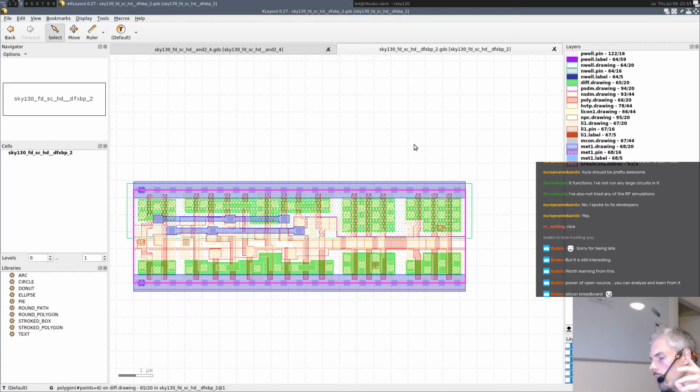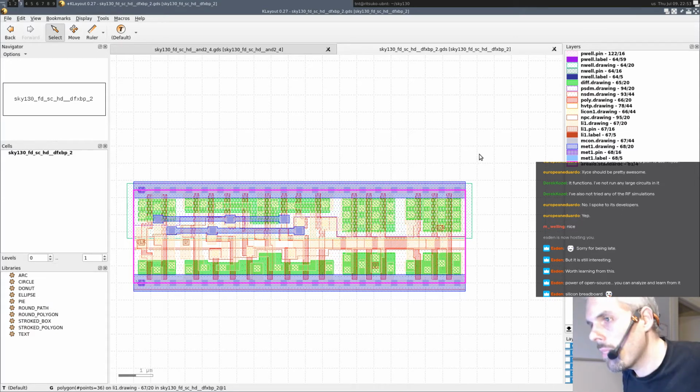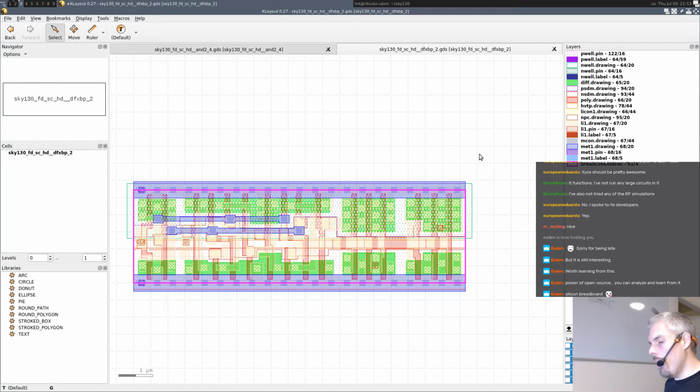But when you stack them vertically, you actually flip it, like you do a vertical inversion, because this is the positive power rail, right? And so you basically want to reuse the positive power rails for the cell above. And so you always have negative, positive, negative, positive, negative, positive, and you just flip that in the other direction, and it doesn't matter in which direction your transistors are built, right? So yeah, I hadn't thought of that at the beginning.